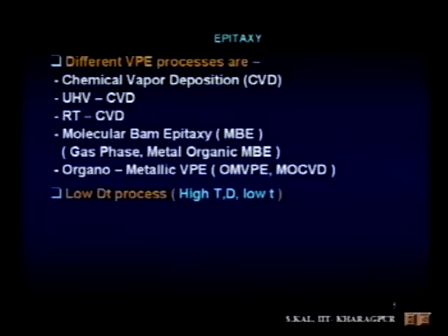You know, in a VLSI, the DT product should be as low as possible to prevent redistribution of impurity in the bulk of silicon substrate. In the bulk of the layer in which you are making devices, their redistribution has to be prevented, so that it will not occupy much silicon bulk area and you can get higher density of the films. That is one aim of all processes.